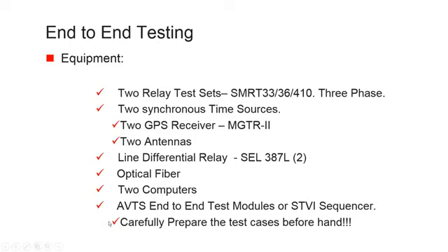My take in all this is this last line here: carefully prepare the test cases beforehand. Don't improvise, and understand fully the system that you're going to test before you go into the substation to do your testing. If not, you're going to end up wasting and losing a lot of time.